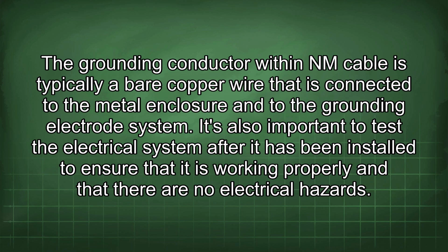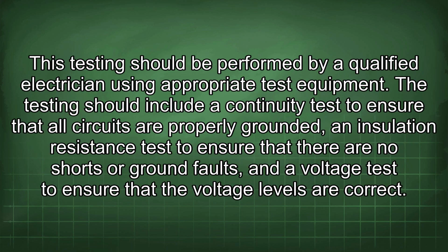It's also important to test the electrical system after it has been installed to ensure that it is working properly and that there are no electrical hazards. This testing should be performed by a qualified electrician using appropriate test equipment. The testing should include a continuity test to ensure that all circuits are properly grounded, an insulation resistance test to ensure that there are no shorts or ground faults, and a voltage test to ensure that the voltage levels are correct.